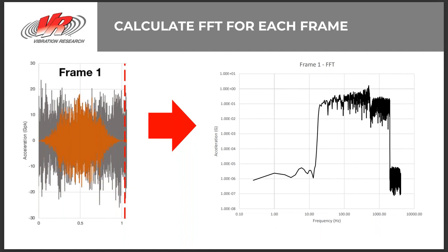There are a few notes that must be made when calculating the FFT. There are certain factors that can be applied to the windowing function for different purposes. If the goal of this process was to simply generate an FFT, a weighting factor is applied to ensure 1G peak of the time domain data is equal to 1G peak on the FFT. So when generating a PSD, the window function is normalized to preserve the input power.